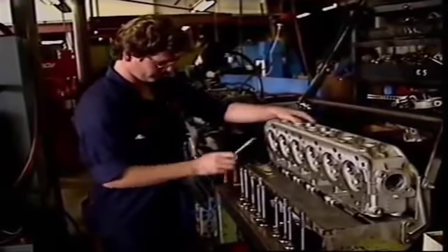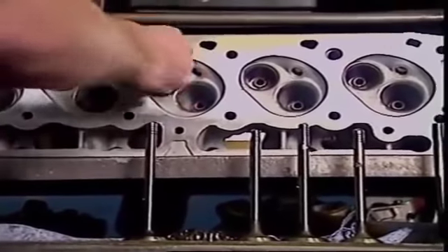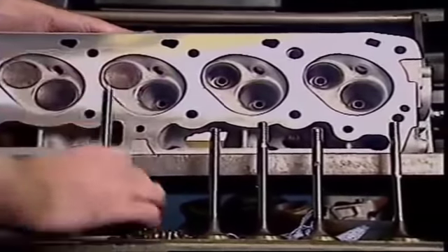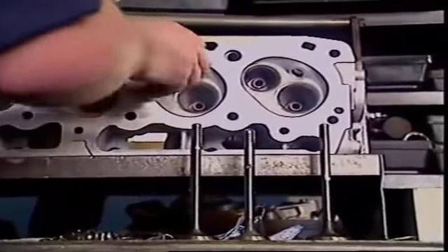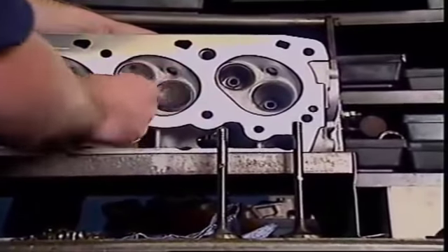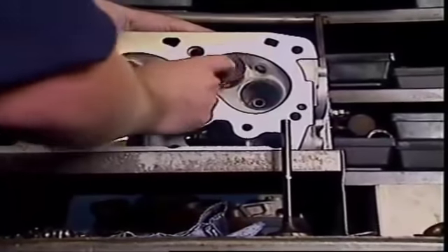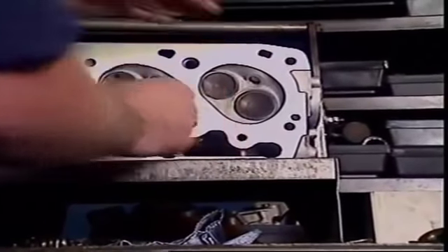As the valve opens and closes, it has a natural tendency to rotate very gradually, so that it keeps seating in a new place. This produces a slight wiping action, which helps keep the face and seat free of carbon. It also helps prevent sticking in the valve guide and distributes heat around the valve seat.